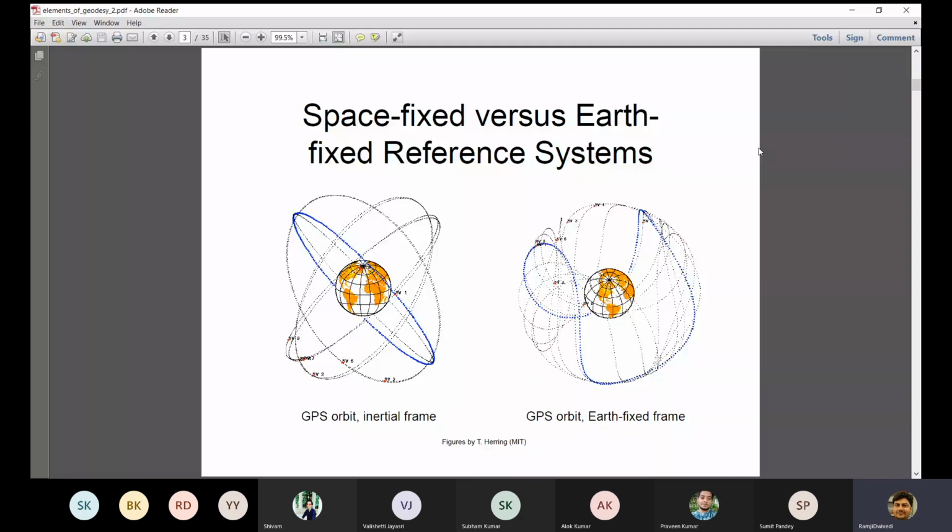By the way, all this measurement, range measurement, and coordinates are the job of the receiver. You simply get the output. That's the black box where you see the output as XYZ or latitude, longitude, height, or NEU. But in the black box, this is how it is working. You get the coordinates of the satellite in ECEF, you get the distance measurements, you solve the equations, and then you adjust. At the same time, you process the least squares adjustment in the black box, and then you get the least squares adjusted values of a particular point.